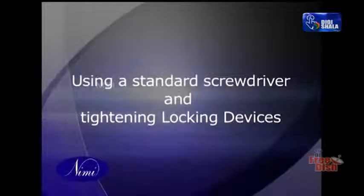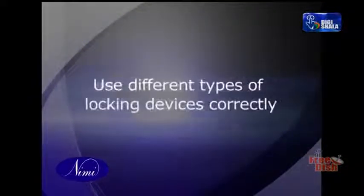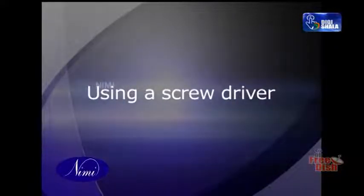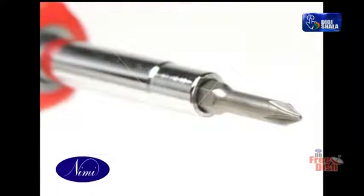Using a standard screwdriver and tightening locking devices. Objectives. Handle a screwdriver and use it. Use different types of locking devices correctly using a screwdriver. Select the correct size screwdriver to suit the screw slot. Select the longest suitable screwdriver with that size of tip.